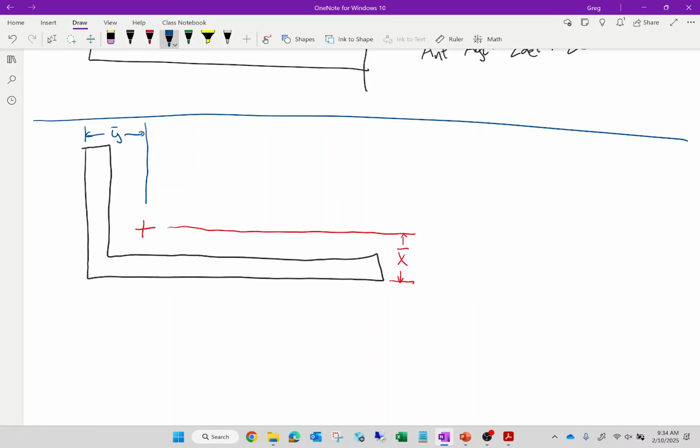You cut a section like this, perpendicular. There's stresses inside, right? But what if instead of cutting a section like this, I cut it like that? The stresses are going to change, right? There's going to be some trig involved. I can relate these stresses to these stresses with a little bit of trig. I seem to remember in trigonometry that sines and cosines are really just coordinates on a circle.